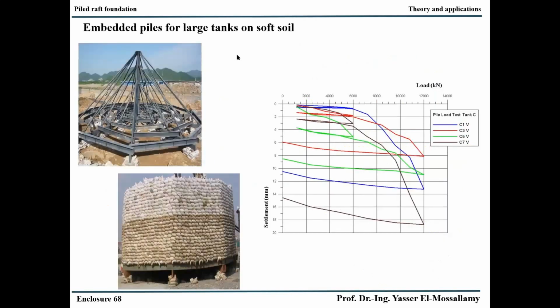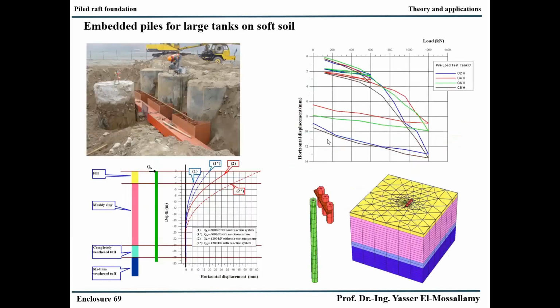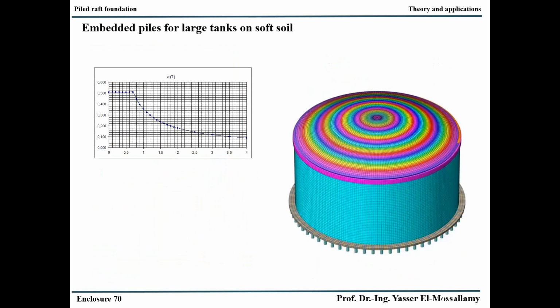Therefore, first of all, again, pilot tests. We have done very good pilot tests, and our colleagues in China developed this huge reaction system using a pyramid triangular steel structure filled with sandbags. But in the end, we can apply our high loads on the piles. We have also done horizontal pile load tests. And our structural engineer modeled the tank very accurately, with each beam and each connection in the tank, and made a seismic analysis to give us the PGA value of the tank.